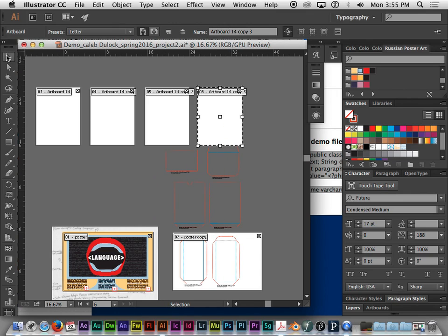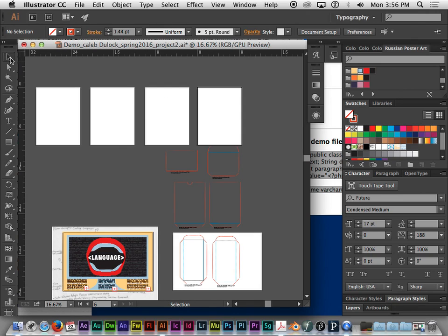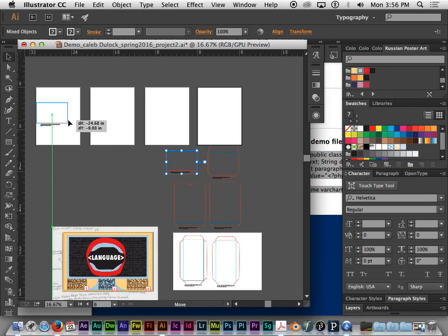But once you get those established, exit the artboard tool. The reason for exiting it that's important, guys, is that if you keep clicking around with that on objects, it converts every object into a new artboard. So you have to be very, very sensitive. It will make a new artboard for every single thing that you click on. So if I clicked on a random shape, it would suddenly design an artboard to fit it. That's great, but it can also be problematic. To exit the tool, just go to a new tool, like the arrow tool at the top of your toolbar, and that'll get you out.